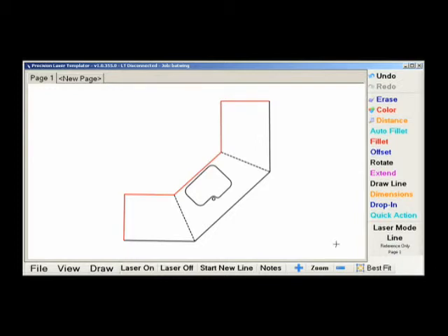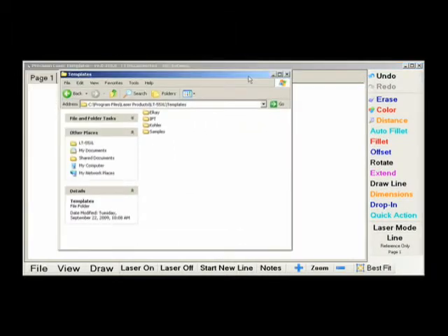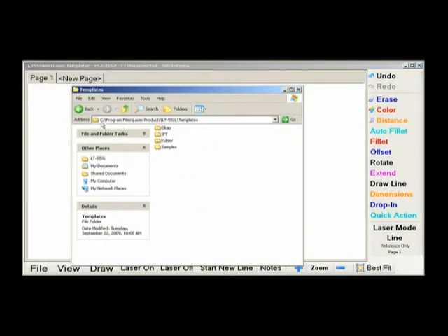For countertop fabrication companies that use a few sinks all the time, you might want to add a drop-in of that sink to our software. To do so, the DXF file of the sink, or any other drop-in you might have, like a special corner or mark that indicates the centerline or dishwasher, needs to go in the program file. That is located at c:/program files/laserproducts/LT55XL/templates.